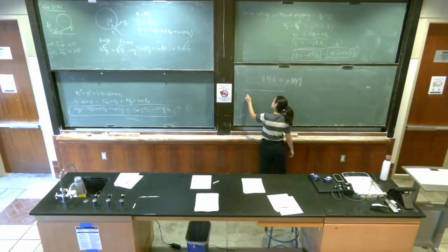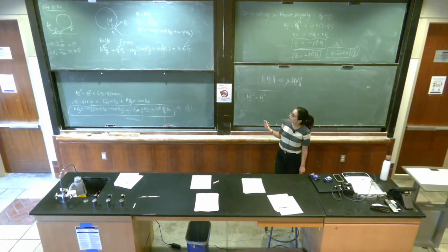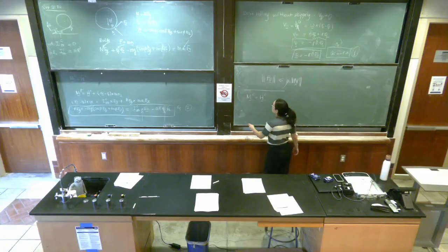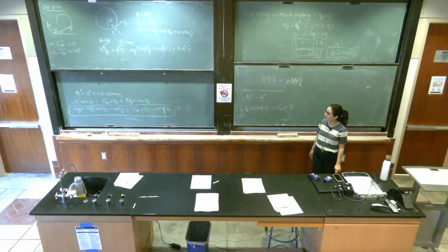MC is equal to H dot C. What is the only force giving a moment about the center of mass? It's the friction force, right? So that gives us RP minus RC cross the friction force, EX, is equal to H dot C, which is ICZZ alpha EZ. So yeah, in the case where ICZZ is 0, you get the friction force equal to 0.